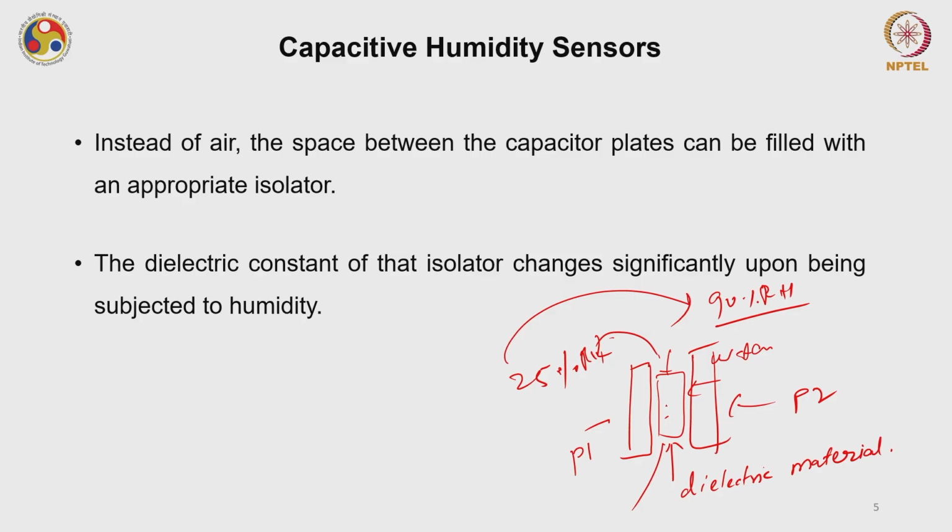Because of this, it will start to swell. And this is the major problem associated with polymeric films which are used as dielectric material. So when it starts swelling, this D is also changing. So it will be very difficult to characterize whether the effect is coming because of this changing D or because of the change in the dielectric property of the material.